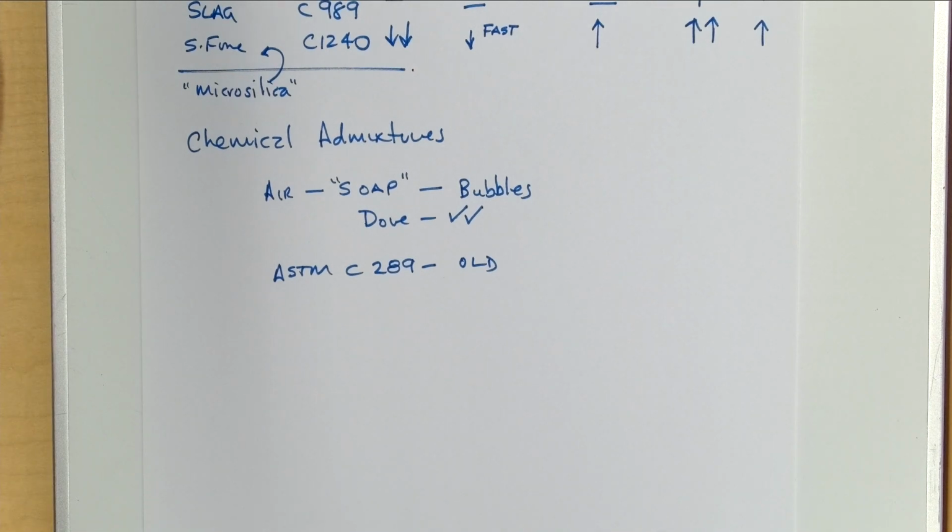So it's not too bad, not old, not new. It consists of a soap that's stable at high pH with a high solids content in the water. And so you will see when we talk about durability, we specify the air content, but what we really mean is we want to know the air structure. So that was our first one.